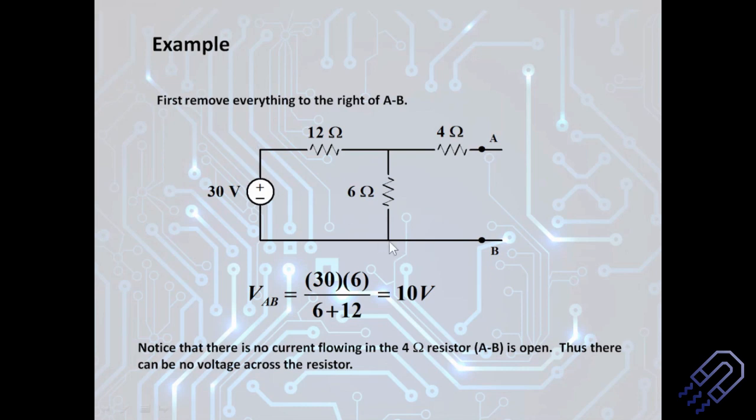Okay, so you can ground it at this particular point, and then across the entire length of this, because there are no other electronic components here, we basically have the potential as 0. Okay, but here it's different. Here it is 30 volt, and then as soon as we cross this 12 ohm, there is a potential drop, and that potential drop is V minus IR. So if I know the current and I know the resistance, I can subtract it from this 30 volt and I will get the potential on this side. Okay, so this is something more basic. I'd like to explain this now so that you are confident about approaching these kinds of circuits.